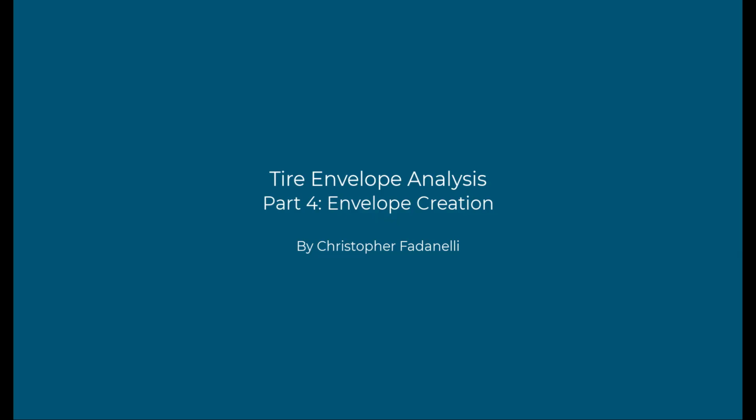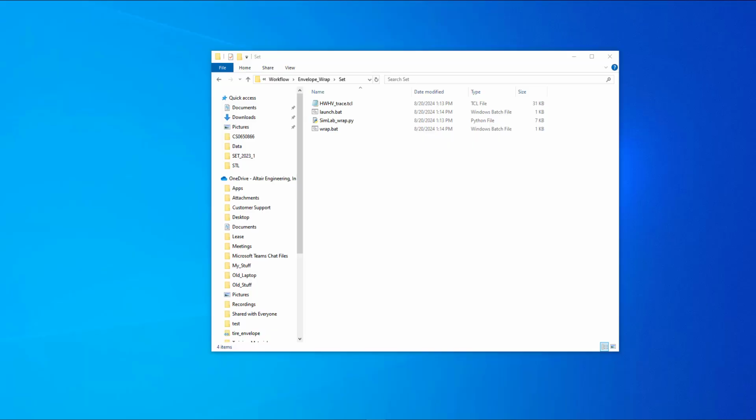So now we have completed our MBD model runs. Now what we need to do is create the trace model of the tire envelope. In the documents, we will have a folder called a set, and it'll include these 4 files: a trace TCL, 2 batch files, and a SimLab wrap Python file. What needs to be added is the H3D from your most recent MotionSolve run of the tire envelope analysis.